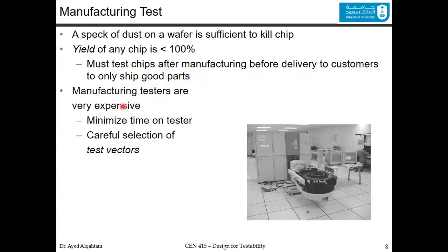Manufacturing testers are very expensive, so you want to minimize the time on the tester, and you should carefully select the test vectors so you can cover as much failure as you can, or as much potential failure as you can.